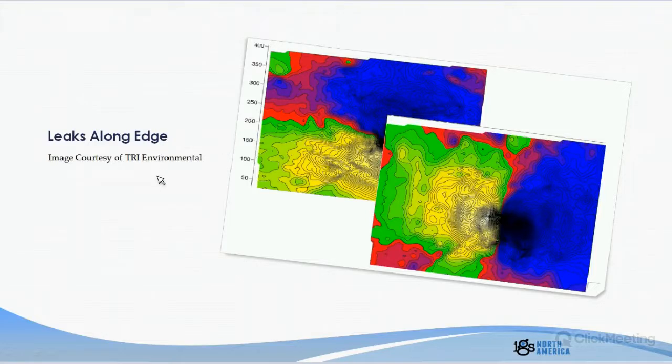So the important thing to realize is that the ASTM doesn't address this, but you have to walk across the leak in order to see it. So you can miss leaks if you're always approaching an edge and you're never walking parallel to the edge.